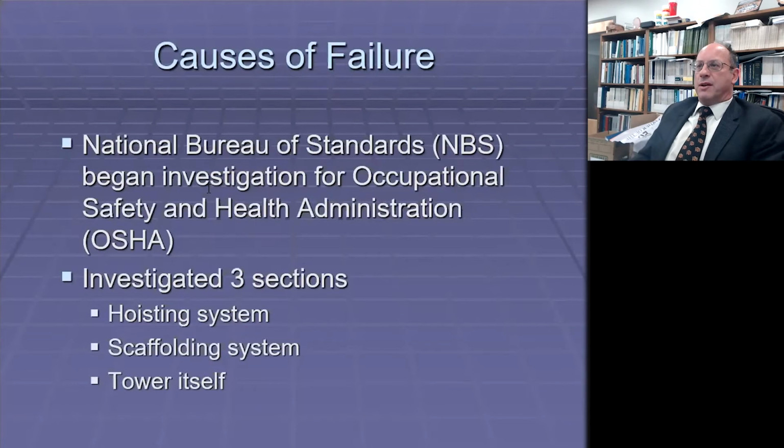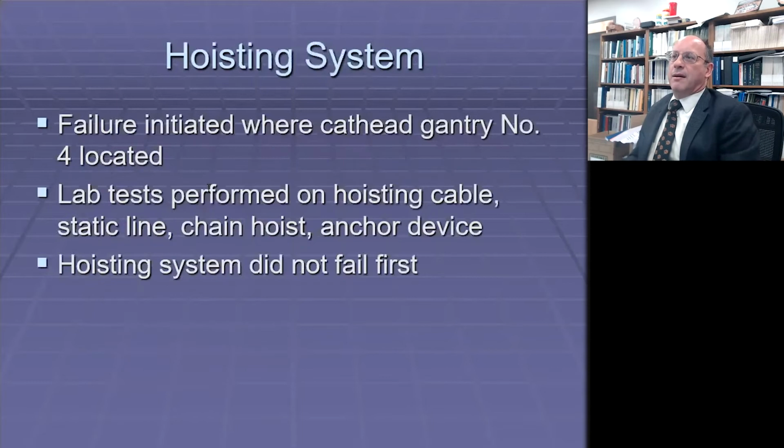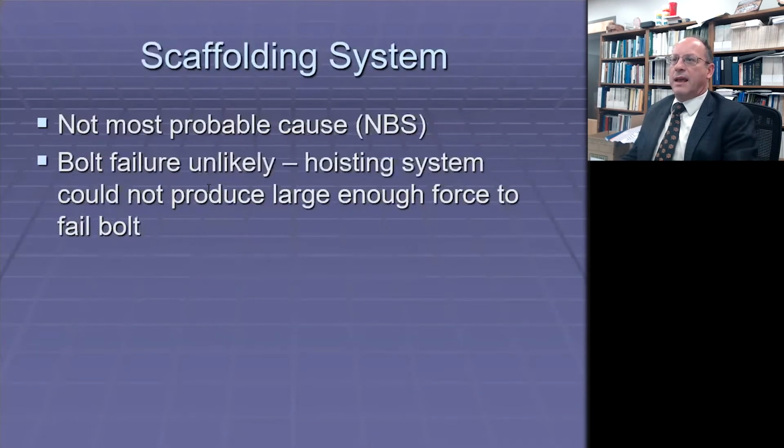The National Bureau of Standards, what's now NIST, in those days would do investigations for OSHA, and they wrote a report. Like any forensic investigation, you look at all the possibilities and then eliminate the possibilities as you go. They noted the forms are held in by bolts, and they did not think that the bolt failure was likely.